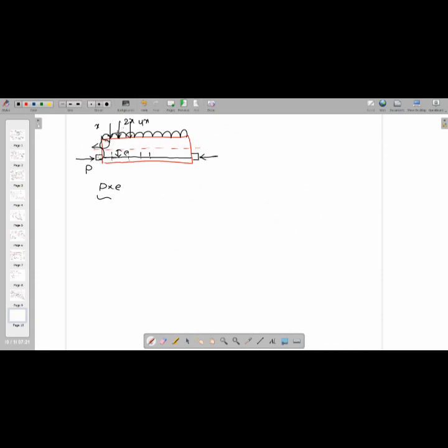Now you are combining these two, and you are drawing the moment diagrams at that point due to that forces, or you are drawing the resultant forces at that point. So the resultant force keeps on changing with the load applied. So that is the reason, sir, actually the tendon will be something like parabolic. But here why there is a shift is because you are taking both the combinations, and also the load is changing at every point. Simran Nazir, did I answer your question?